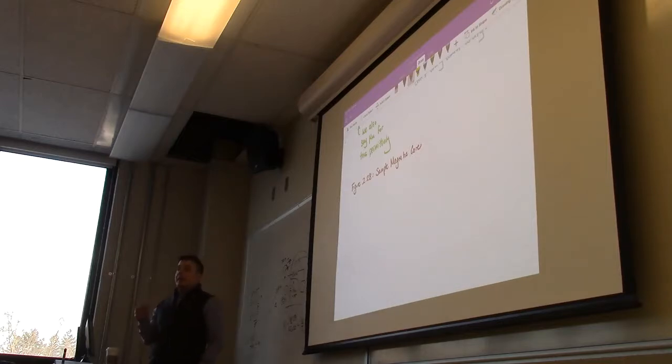Even if you don't have a magnetic core, you can still have leakage inductance. Let's say you have two sets of coils with no magnetic core in between them, they're just sitting next to each other. You would still have magnetizing inductance, which would be flowing through the air, through the separate coils, and then you would have a leakage inductance.